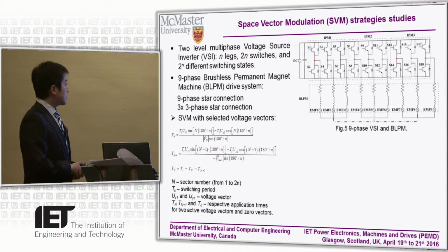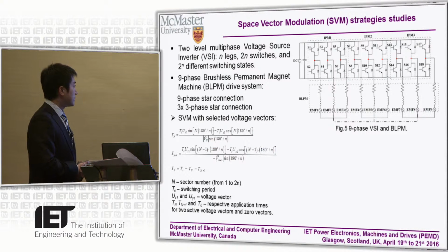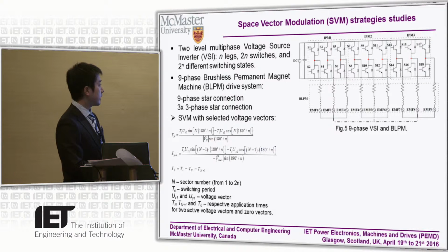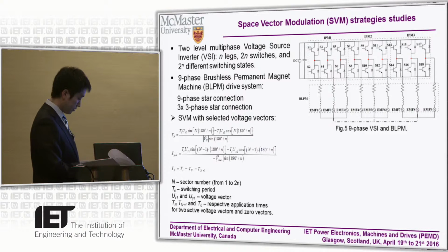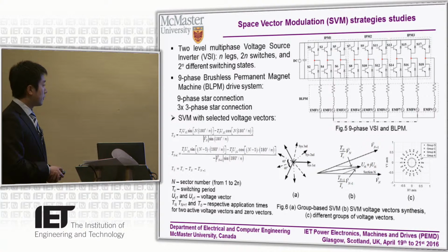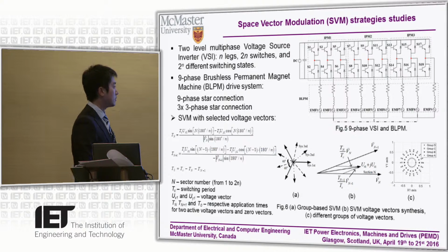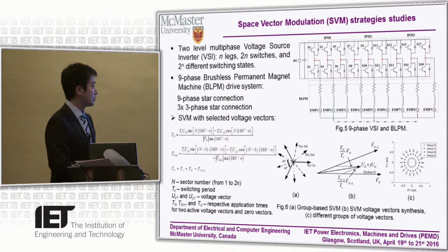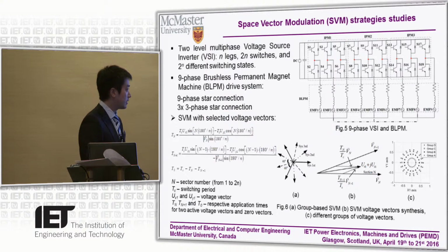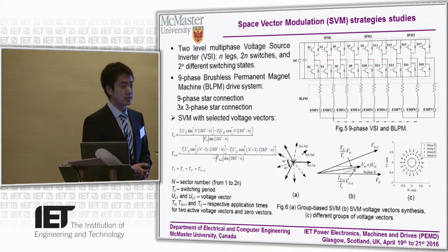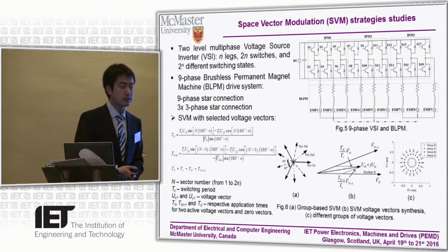These are the synthesized voltage vector equations for the SVM strategy. It's not new. Figure 6a shows the combination of three 3-phase systems to make a 9-phase system. In the conventional 3-phase system, the phase displacement between successive phases is 120 degrees.